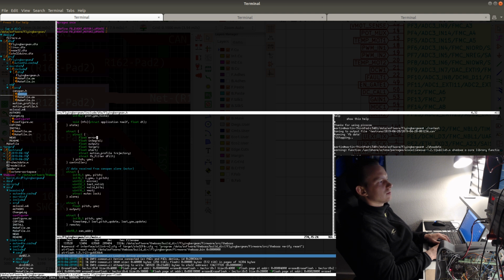I'm going to be using derivative on error instead of derivative on value because that's just easier to simulate in MATLAB. But there is an equivalent form of PID controller where you just use the derivative on value, but then you have to switch the sign in front of the derivative. And it basically has the same effect, except that it's not as sensitive to set point changes as the derivative on error version is, which is the standard version, by the way. That's the typical PID controller that you see in like 95% of cases.